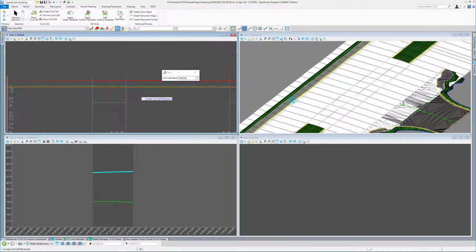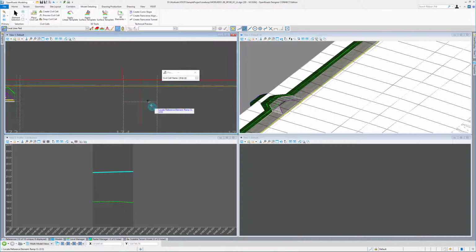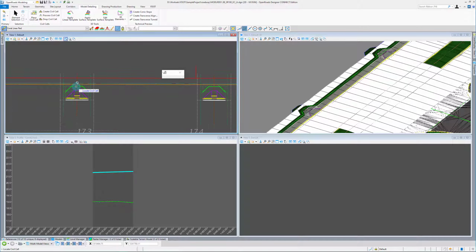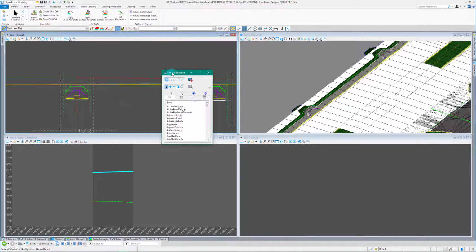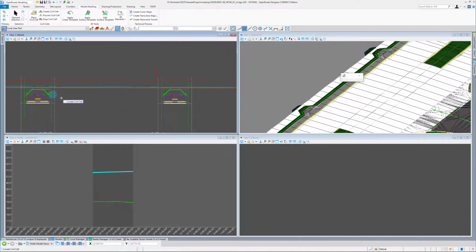Obviously when we look over here, once it places it, we're going to have some stuff on top of each other. That's fine. We can just move over here, do our other one, get those in here, and then we'll fix everything up. Alright, so both got placed. Remember to drop them. Civil cells, I'm just nervous about having civil cells in here. So this one, I believe it's still part of a civil cell. It is. So I'm glad this happened because sometimes you try to drop it and it won't let you.